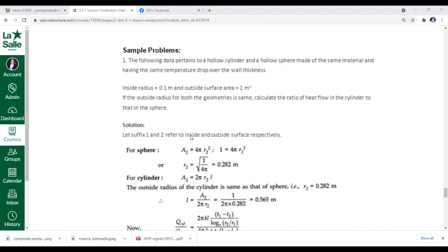Again, you want the breakdown of the resistances for the sphere? Okay, Drexel, the principle of heat transfer, whether you have a flat slab or a cylinder or a sphere, is the same. The amount of heat transfer through one particular resistance would be the same as the amount of heat transfer through another resistance, as long as these resistances are in series, in particular when we speak of the cylinder and of the sphere.